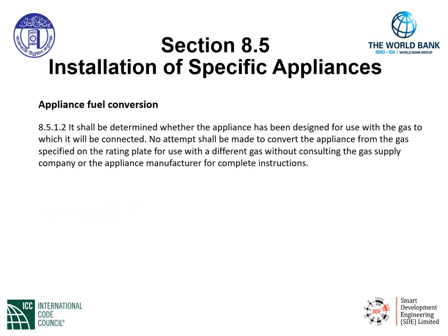Appliance fuel conversion needs to be considered when you are converting from one fuel to another fuel. We have a requirement in our gas code, section 8.5.1.2, and it states the following. It shall be determined whether the appliance has been designed for use with the gas to which it will be connected.